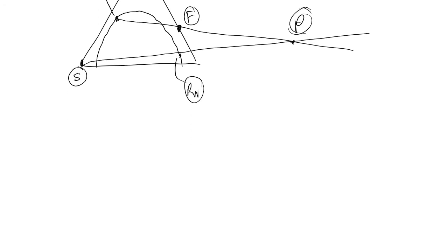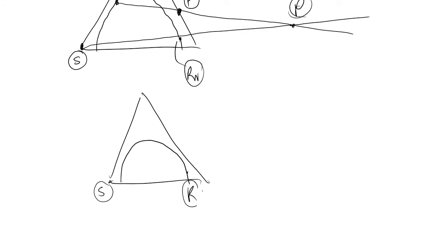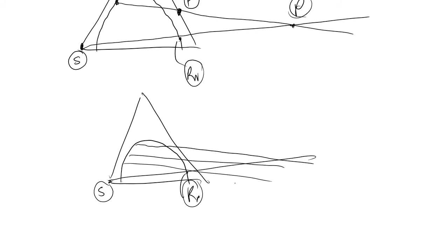Alternatively, another method of evaluating the pivot point P is based off the given data you'll commonly have from the tie lines. If we extend our tie lines out, we'll have a tie line that hits our operating line S R_n at a point farthest to the right. And whatever point this is, that's your pivot point, not R, but rather P.